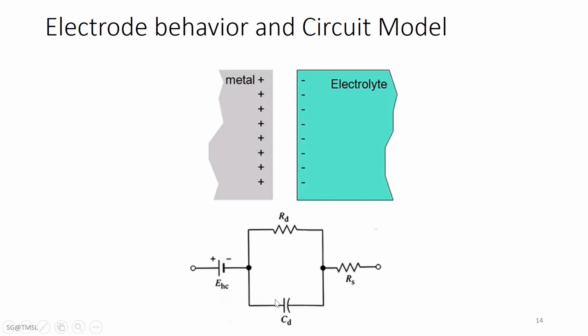And this is the equivalent circuit of the biopotential electrode in contact with the body, comprised of a voltage in series with the resistance capacitance network. The DC voltage on account of this difference in electrode potential is known as the electrode offset voltage.